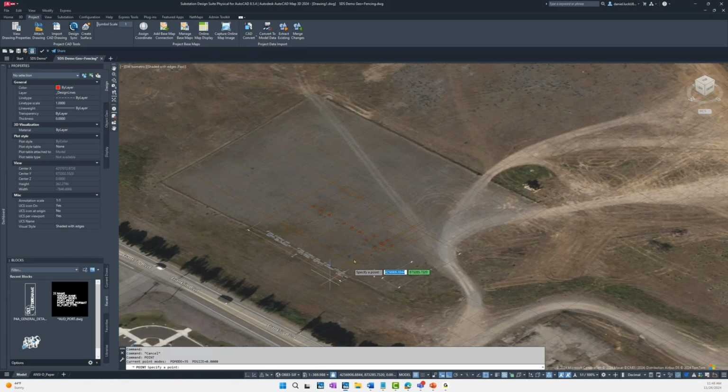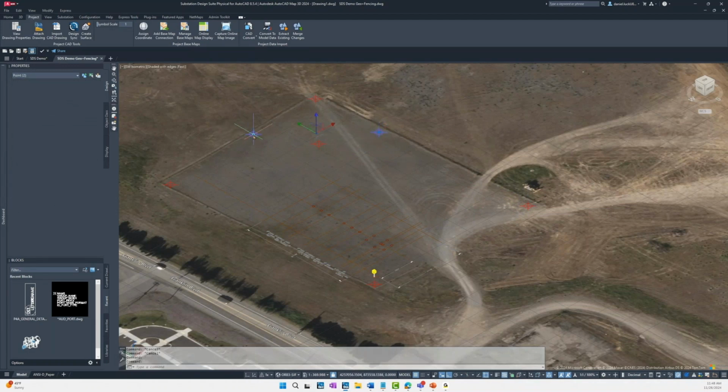I'm going to create a few points using the point command to accomplish this. And I'll just drop a few of these down. Maybe one in the middle, over here. These points then can be modified. So let's say these two are at, over here in our properties panel, we have the Z elevation. Let's just say, hey, this is 5 feet up. And this one is, let's say 10 feet. I know that's pretty dramatic, but for the sake of the demo here, it provides a nice visualization.